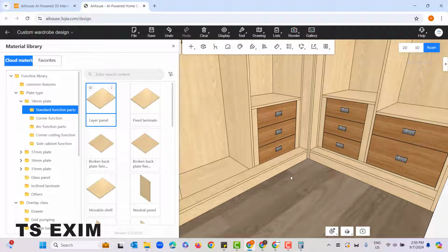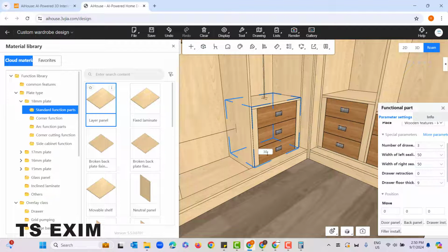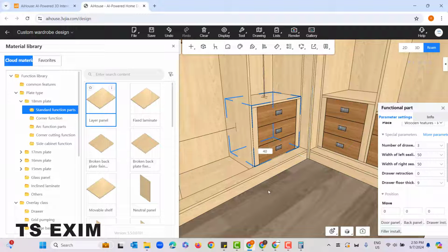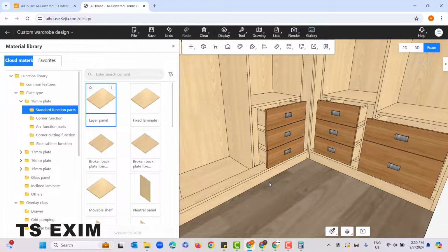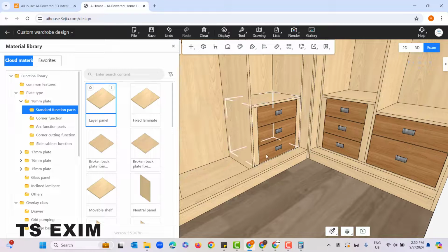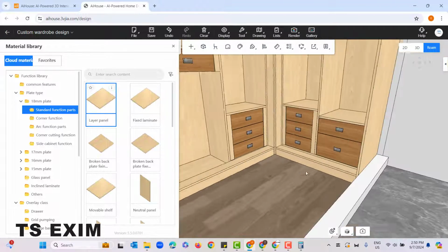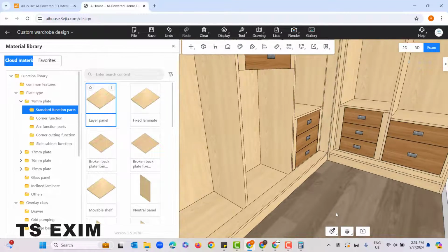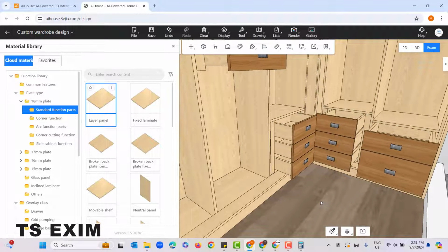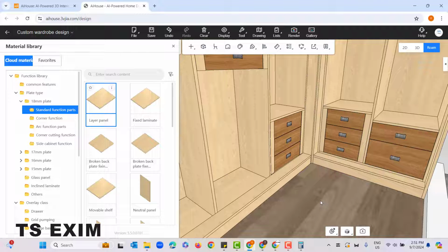If it is still overlapping, you can increase it to maybe 40 mm, as long as the door won't overlap with the feet. Around 30 to 40 mm. Then you can press O to open the door, and press O again to close the door.